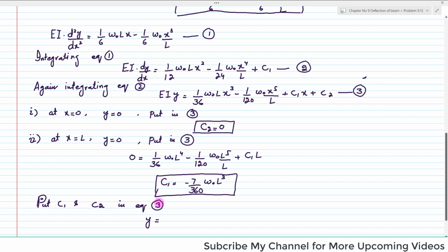So you will get y is equal to W naught over EI, taking W naught as common, and this equation will become equal to 1 over 36 L x cube minus 1 over 20 x5 over L minus 7 over 360 L cube into x.